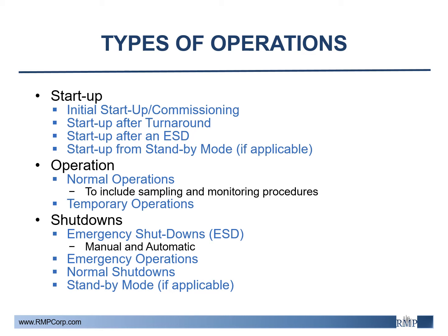Lastly, temporary operations and emergency operations. Typically, temporary operations include draining or filling during normal operations. The system should be analyzed to determine what type of mode the system should be in prior to starting a temporary operation, such as standby or complete shutdown, and what steps are required prior to returning it to normal operations.